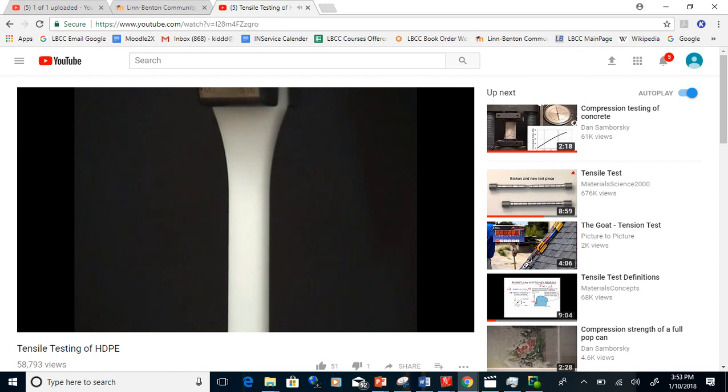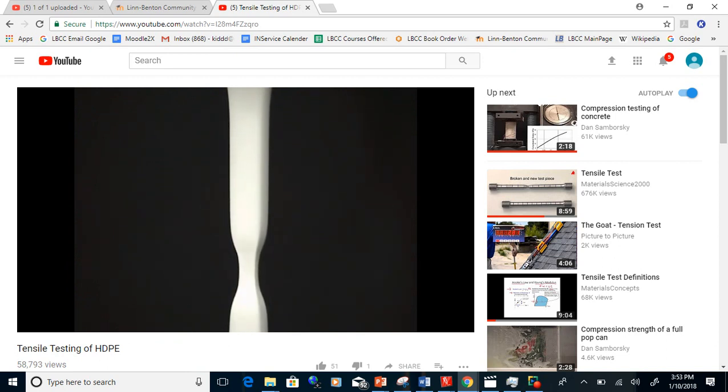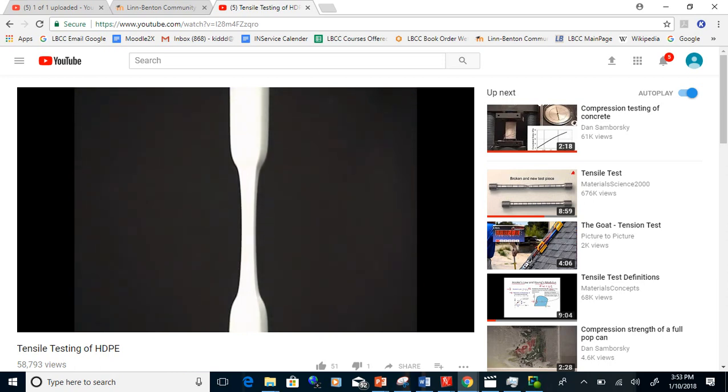You can see this is very, very ductile compared to metal, but it'll do the same sort of thing. It'll eventually thin out and neck somewhere, and then it'll fail. It seems like it stretches much more. Yeah, it's more ductile. They've got organic bonds as opposed to a crystalline kind of bond. It's like pulling bubble gum. Different bonds.